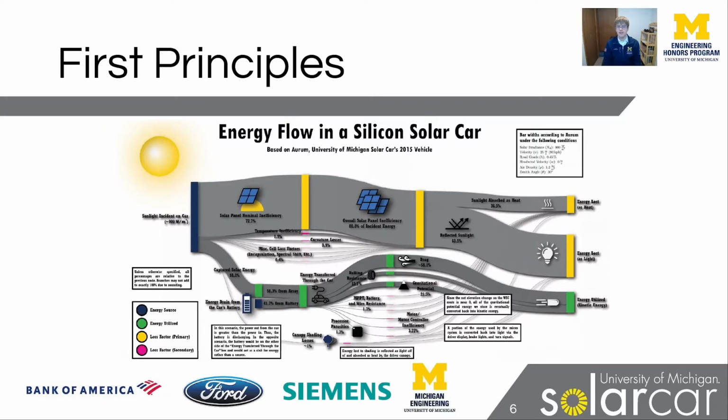We can't really change the nominal inefficiency, short of spending more money on better cells, which isn't always an option. But designing your array and using good engineering practices can help to minimize your losses to other factors and maximize the amount of energy that the car gets to put down onto the road.